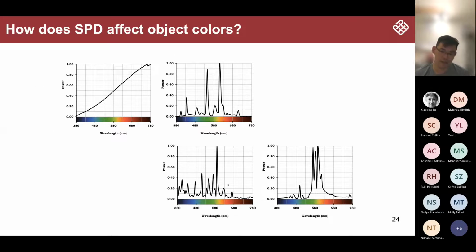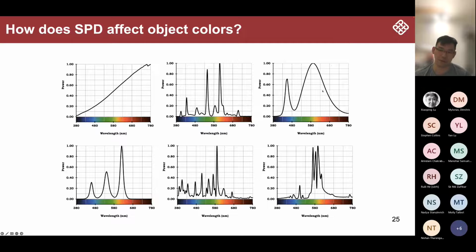We mentioned that the spectral composition will affect the color match, but it will also affect the color appearance of the object. This is what we call color rendering. These are the spectral power distributions for conventional light sources, and you can see that they generally have a continuous spectrum. And these 2 are the spectral power distributions for LED sources. You can see that we can make the spectral compositions much narrower, or make the spectral power distribution not continuous, in comparison to the conventional sources.